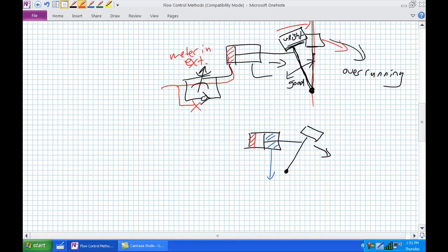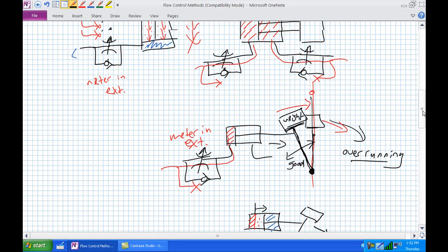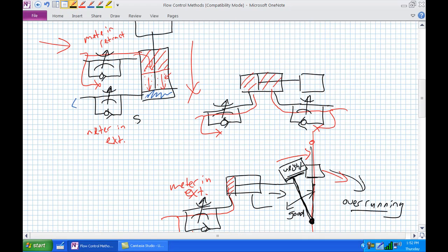That's draining as fast as possible. We've got another cavitation event where that liquid can enter the gaseous state. It's basically separating the piston face from our cap fluid there. So that's an overrunning load. So for an overrunning or a suspended object, meter in is not such a good idea.